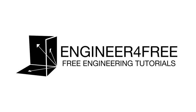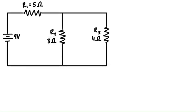Alright guys, welcome back. In this video we're just going to solve this circuit to find out what the voltage drop and current across each resistor is, and then we're going to come back and verify our results using Kirchhoff's voltage law. So to get started, we need to identify what the equivalent resistance is from this node to this node. We can draw on an equivalent resistor if it helps, and we can even shade in the different nodes if that also helps us to identify the difference between the nodes.